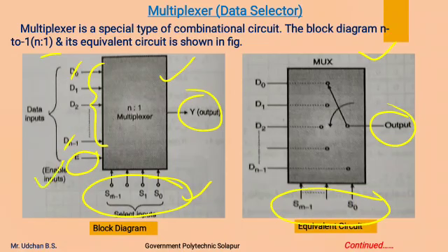If the enable input terminal is not enabled, we will not observe any input line onto the output line, irrespective of the status of select inputs. It means that if we want to perform any operation from a given multiplexer, we have to enable that multiplexer before applying any input. So this enable line acts as an on off switch for this multiplexer, which is very important.